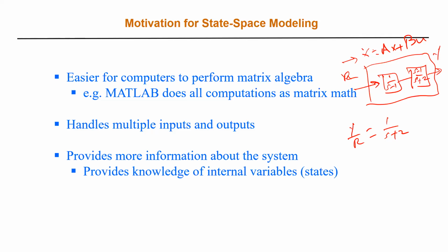Now, what is the order of the system supposed to be? Second order. But because of pole-zero cancellation, it appears as first order, and from the input-output stability point of view, the system is fine. This is a very important point.